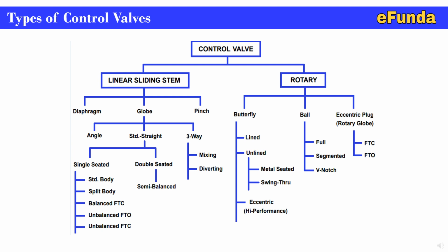Further, for these rotary types, it's actually a streamlined flow path. That means these are connected in line as a flow path valve. High recovery valves are considered as a rotary valve. Here there is more capacity and less packing, and they can handle slurry as well as abrasive services, with high rangeability, a flangeless valve, and an integral bonnet. Now we will see the major types in brief.